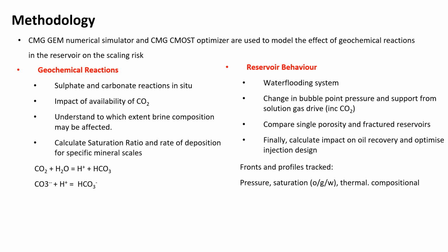Methodology: the CMG GEM numerical simulator and the CMG CMOST optimizer are used to model the effect of geochemical reaction in the reservoir on the scaling risk. Geochemical reactions include sulfate and carbonate reaction in situ, and the impact of availability of CO2. We seek to understand to which extent brine composition may be affected, and calculate the saturation ratio and deposition rate.